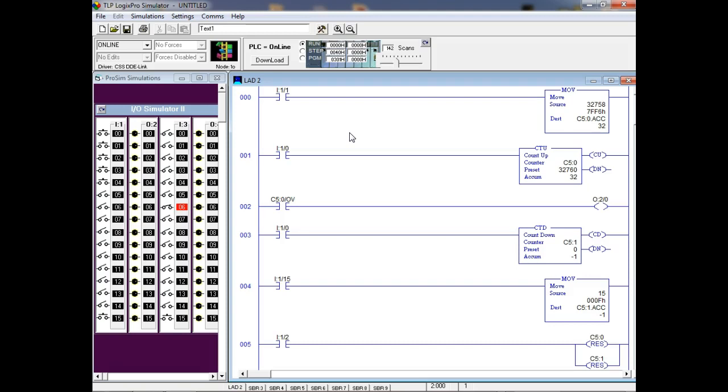UV, I think. We'll look and make sure. Then if this accumulator goes below negative 32,768, then we get an underflow. So it doesn't mean you completed the count. Understand, I don't have this set up for this one, but here's the overflow right here, right?